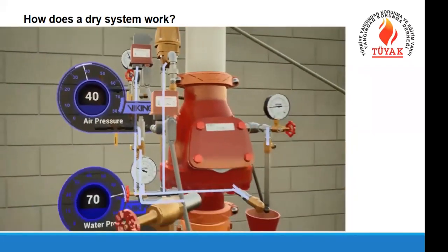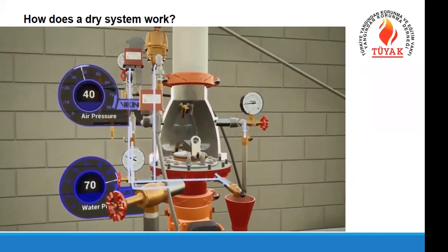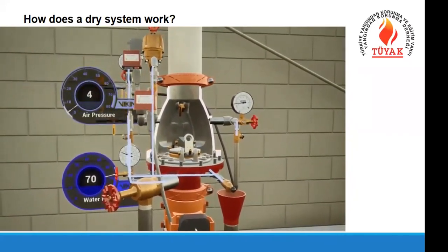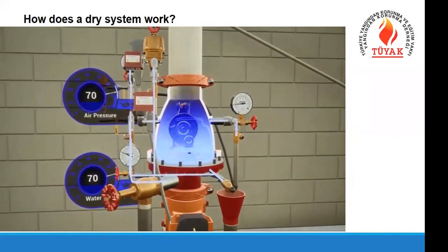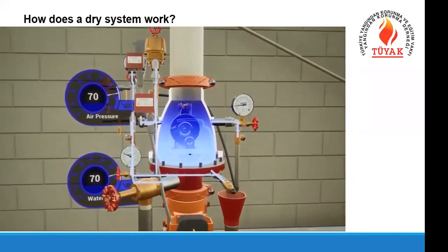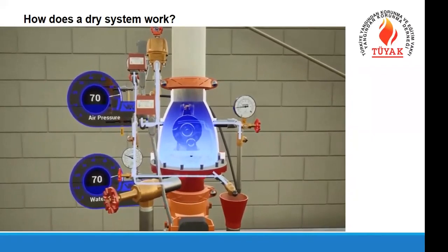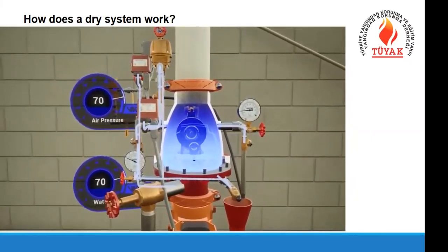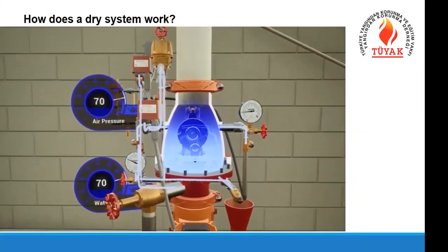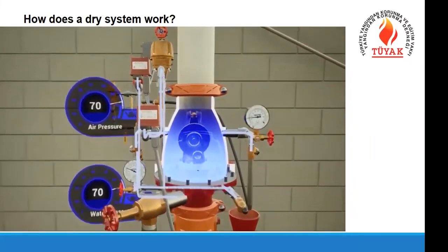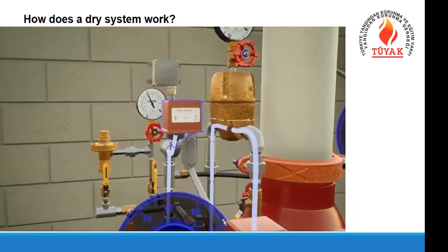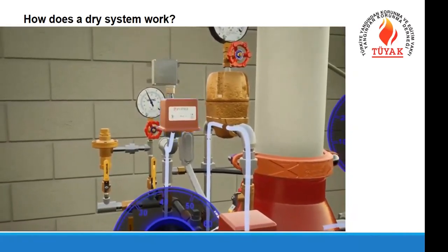As pressure reduces in the outlet chamber, the differential in the valve is equalized to a point that the remaining air pressure in the system cannot hold the clapper closed. The clapper is pushed open by the incoming water supply and then securely latched out of the way. Water flows through the valve and trim piping. The water flow alarms are activated.